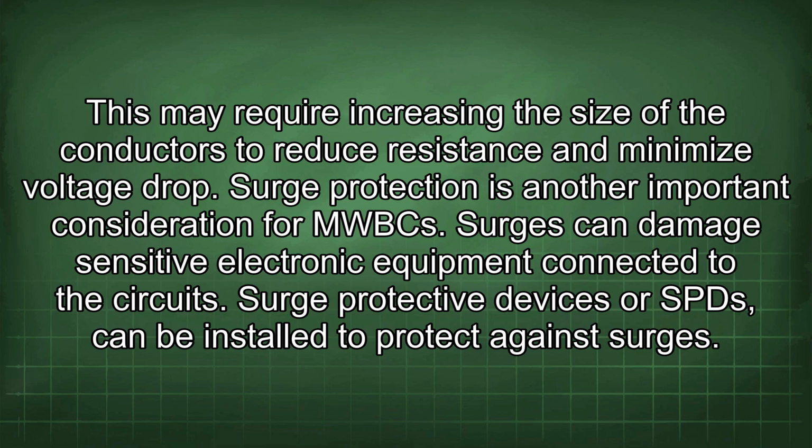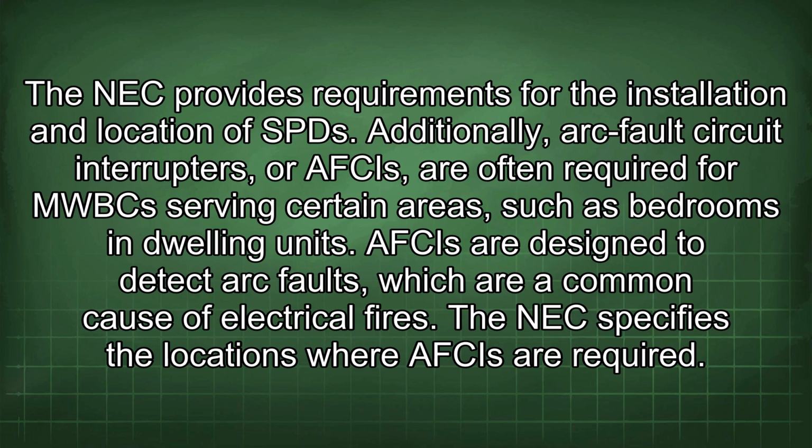Surge protection is another important consideration for MWBCs. Surges can damage sensitive electronic equipment connected to the circuits. Surge protective devices, or SPDs, can be installed to protect against surges. The NEC provides requirements for the installation and location of SPDs. Additionally, arc fault circuit interrupters, or AFCIs, are often required for MWBCs serving certain areas, such as bedrooms and dwelling units. AFCIs are designed to detect arc faults, which are a common cause of electrical fires. The NEC specifies the locations where AFCIs are required.